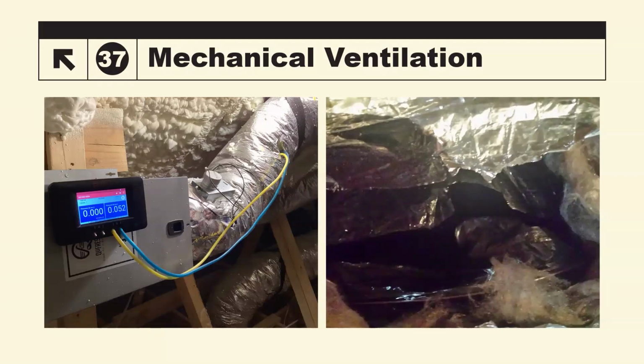And so when that happens, in my opinion, you've got unwanted fibers from the insulation, and/or the attic air itself is what's coming in as fresh air, and that's nowhere near fresh air. So thankfully, the manufacturers have now caught up. They have inline test ports. They have static pressure points that you can actually attach hoses to, and then you can convert that to CFM using some of their tables for converting.